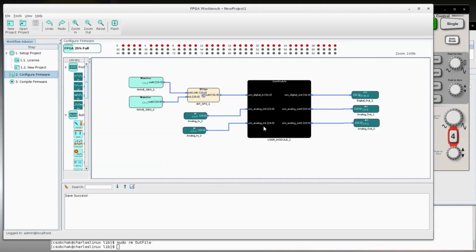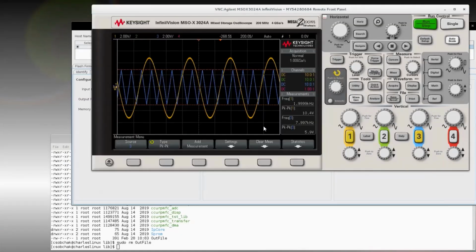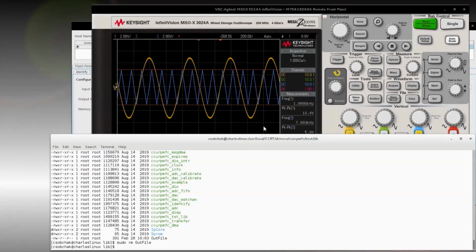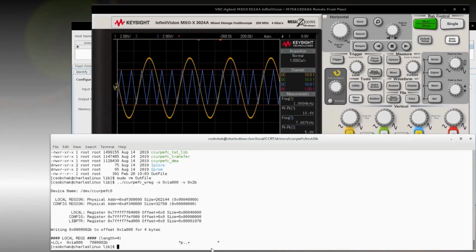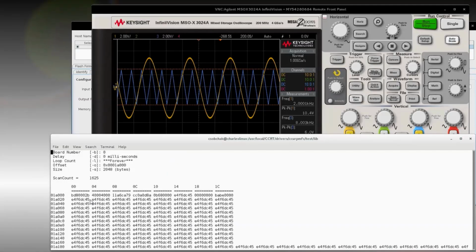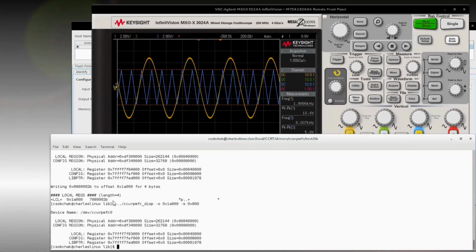So now we'll go into the FPGA and we will do some commands to control the FPGA's RAM. And if you see down here, we're going to first turn on the recorder, which is basically like pressing record, and then we will show some of the data that's being written into the FPGA RAM. And again, these will be 32-bit registers that are written, and the upper 16 is the sinusoid and the lower 16 is the triangular. And now we just switch some mode bits.